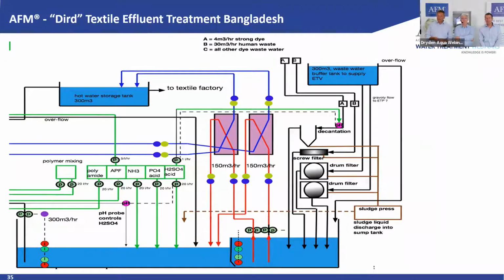Now, Howard, he has, of course, a brilliant idea. He said, okay, let's take this blue water, the filtered water that we need for the process, that we anyway have to heat up to high temperature, which has only maybe 20 degrees. Heat this water up and cool the wastewater down. So with this, we have a big energy recovery. We are talking about 5 megawatt. So that's 500 liters of oil per hour, right? It's huge. That also made a big payback of it.